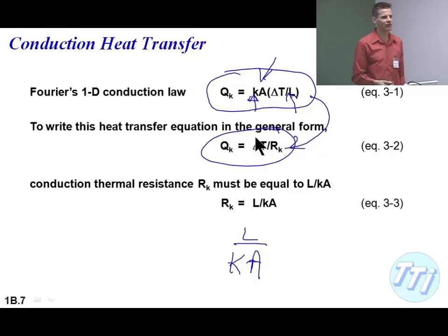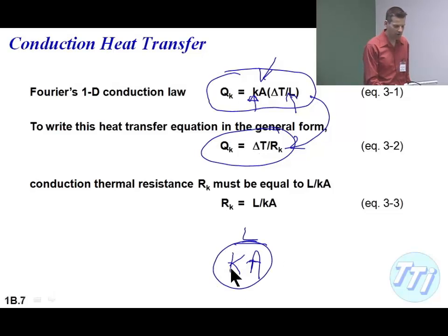Let's say you're trying to determine where to place the power supply in a chassis, and you've got it on a heat sink. You're just trying to figure out, well, what kind of gain do I get if I take the power supply and move it from this corner of the box, maybe to the center? Or maybe that's a decrease in performance because now, if the heat's got to go to the outside of the box, I move the power supply to the middle, I've increased the path length. So if I want to dump the heat to keep the same thermal resistance, maybe I've got to look at a heat sink with a different thermal conductivity or a different area. So having a simple equation like this, you can do some quick back-of-the-envelope calculations without having to run a computer code, without building a test.